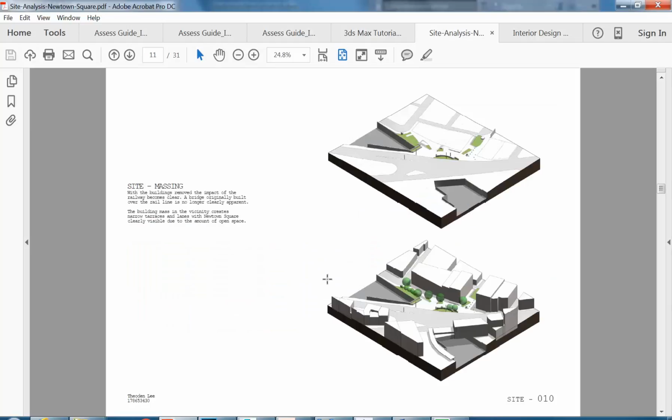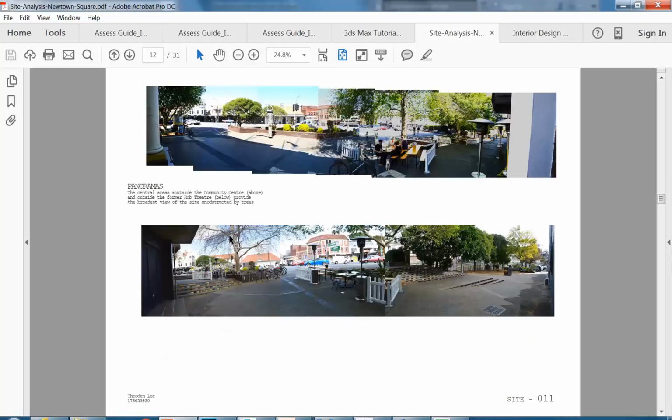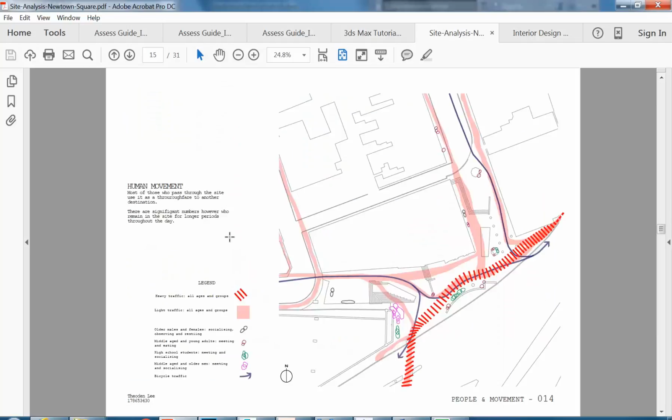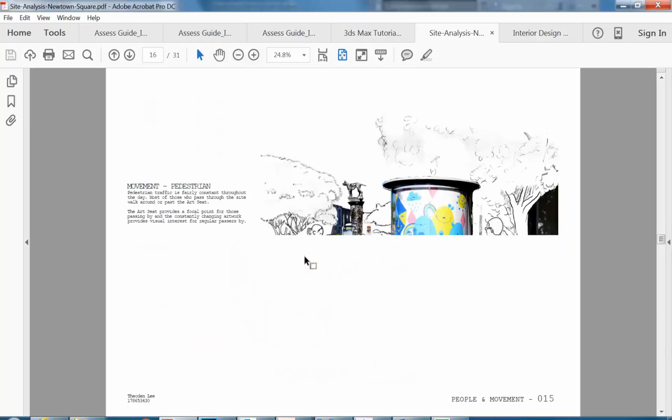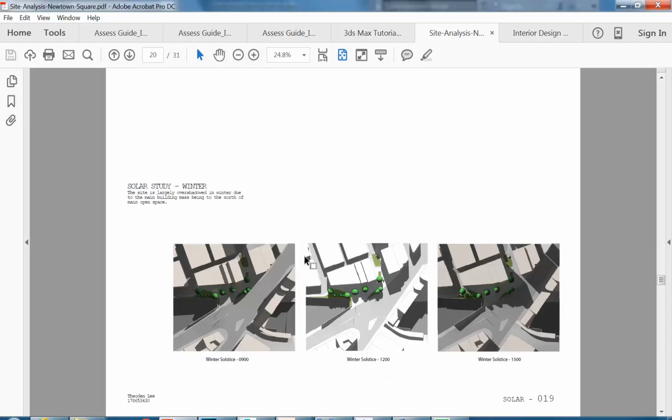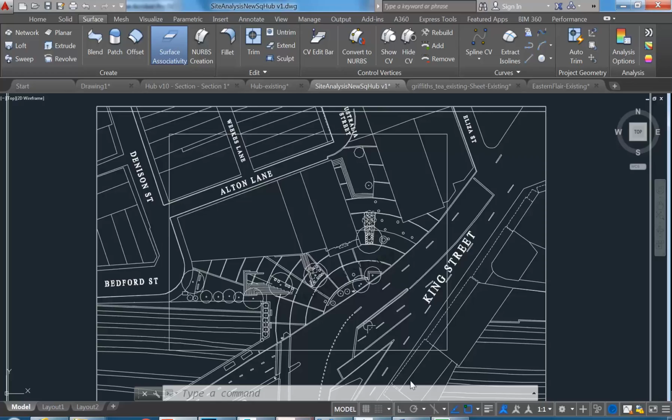And so then I did, though, bring those AutoCAD files into Revit and use them for the basis of these massing studies. And I've got some more of those I'll show you later, but again, here this is just more AutoCAD brought into graphics software to do different things. And this is my terrible drawing, but here we go. So there's the massing again from Revit, but based on that AutoCAD line work. So that's an important process you need to understand.